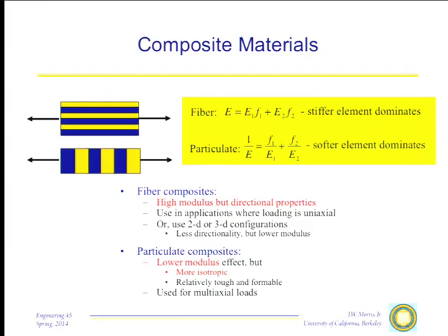They had grounded a 757 down in Dallas a couple of years ago because a baggage truck, not too ferociously, ran into the side of it. Well, if it's metal, you get a small dent. If it's fiberglass, you get a crack that runs the length of the underbelly. You've got to ground the airplane until you can replace the whole part. I had a fiberglass car. In fact, when I came out here, a Lotus Europa, great car, fiberglass, very, very light. But if anybody banged the side of that, you were looking at just a really major repair because of the extended damage to the fiberglass.